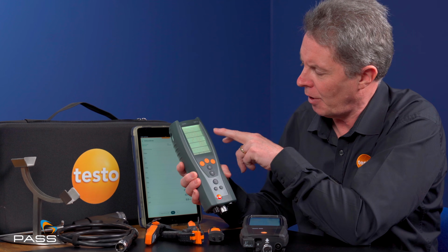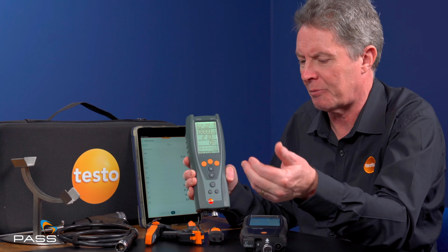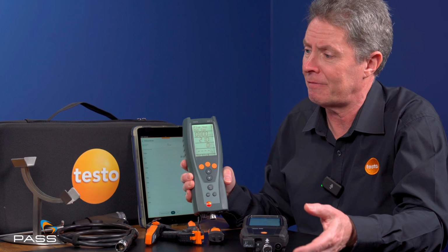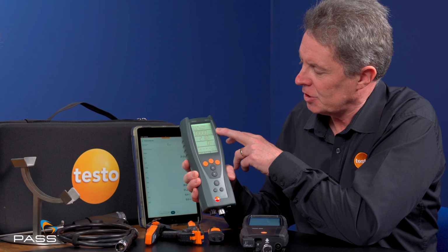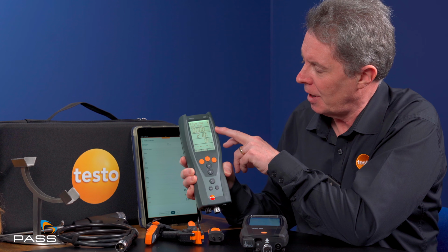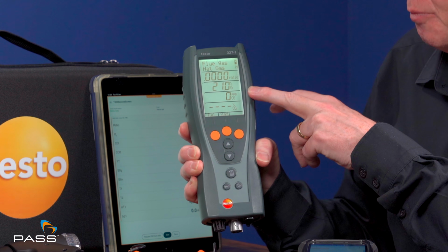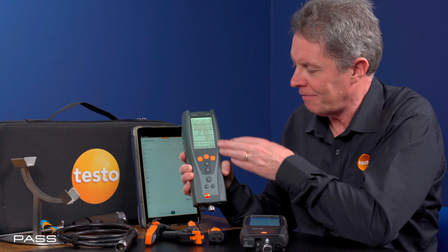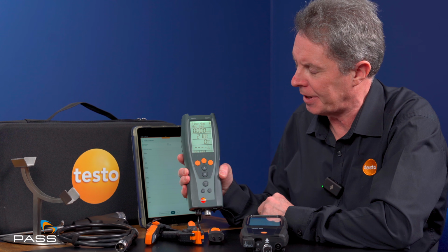For example, I always like to see the ratio as the top line, because it's one of the key measurements. Everybody, if they're installing a boiler, the manufacturer will probably give a baseline ratio figure you'd expect. Which ratio is that? So the ratio is basically the ratio of the O2, the oxygen, to the CO. It's displayed there. I then like to see the O2 value, and then the CO, CO2, and so on. So I have the flexibility in a Testo device to set that running order up as I like it.